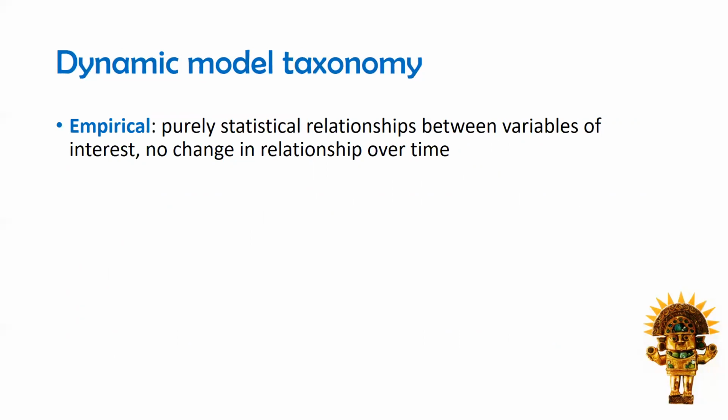One example of an empirical model might be a proxy relationship, such as we try and use between turbidity that we record from high frequency sensors and either suspended sediment or total phosphorus. So we use an empirical regression type relationship with these high frequency measurements to get a dynamic time varying assessment of suspended sediments or total phosphorus, but we don't have any ability to look at changes in the relationship over time. So proxies, an example of an empirical modeling approach, certainly very useful, but also limited, especially for long-term simulations.